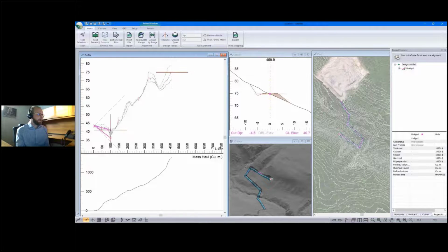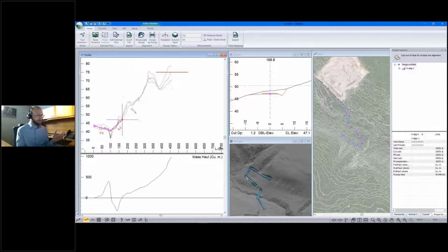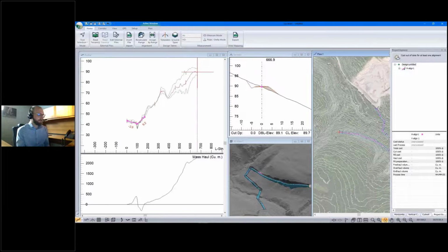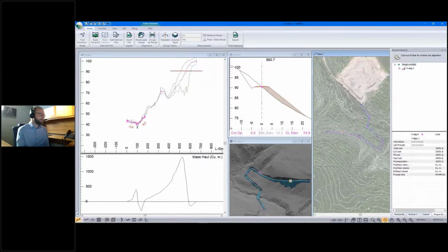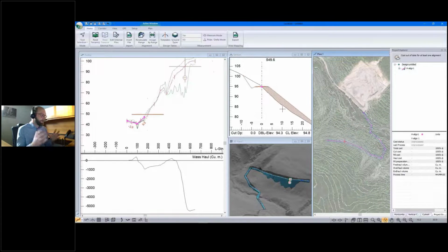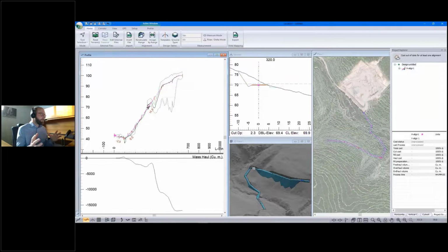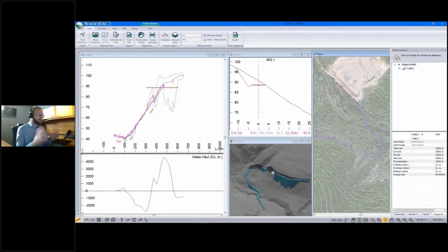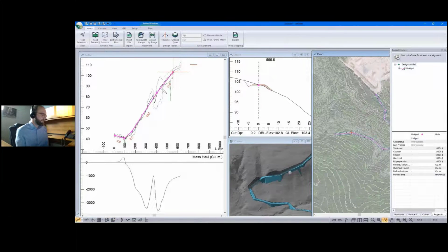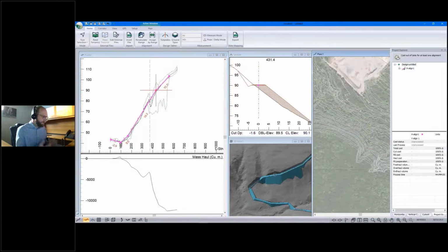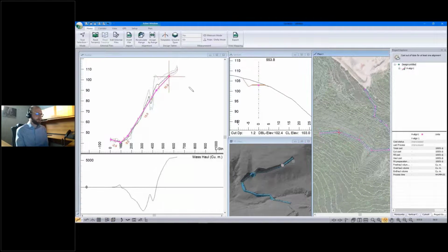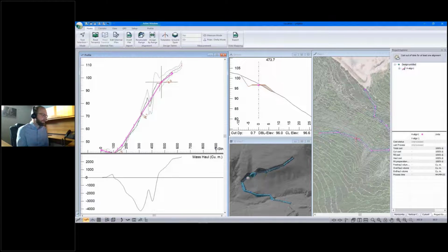Now, as a first step, and everyone's got different personal preferences for how they approach these things, but I'll usually do my roads in little segments, and I'll try and nail them down as best I can as I go. But I'll start with the horizontal, then I'm going to start adding the vertical. And as I add my vertical alignment, I'll take into account my cuts and fills, pay attention to my cut slope, fill slope, etc. And I'll probably have to adjust the horizontal as well. If it's any kind of terrain with any kind of complexity to it, it's wiggling around to find that best place.